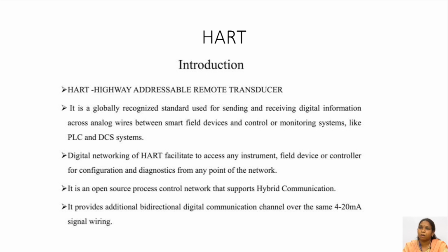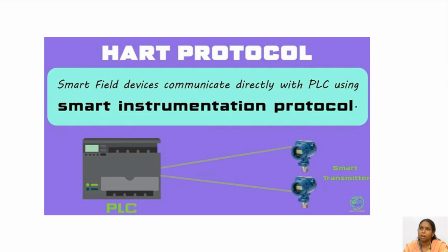Digital networking of HART facilitates access to any instrument, field device or controller for configuration and diagnostics from any point of the network. It is an open source process control network that supports hybrid communication. It provides an additional bidirectional digital communication channel over the same 4 to 20 milliampere signal wiring. So, HART protocol can be called a Smart Instrumentation Protocol, where the smart field devices communicate directly with the PLC